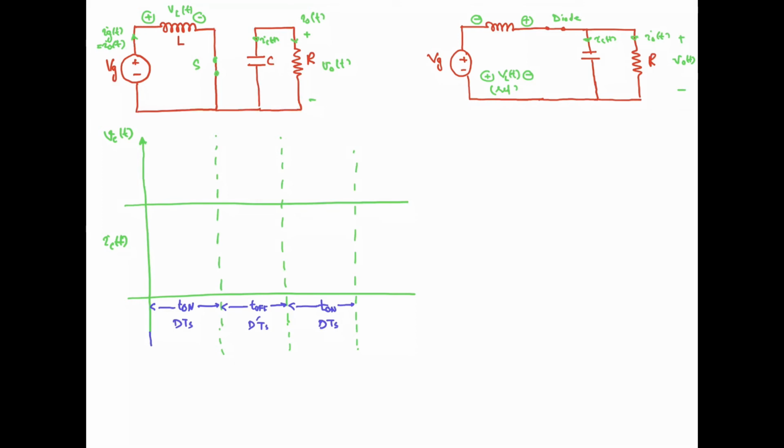So I am going to sketch it like that, this is equal to minus V naught by R, the average capacitor current in this interval. And in the second interval, the capacitor is charging. And what will be the capacitor current? So total current is this one, IL, that is the inductor current. Out of that, the average current at the output is I naught, so average current through the capacitor is IC. So from here I can say that this capacitor current IC will be equal to the inductor current minus the load average current I naught.